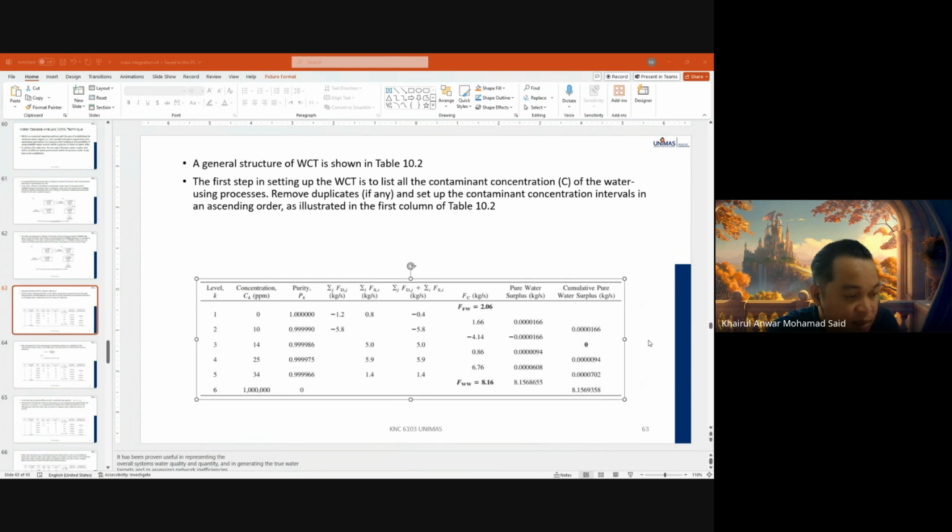The answer is A. Yes. Limiting concentration allows us to define the maximum permissible contamination, opening up the maximum degree of freedom for water reuse. If we only record current operating concentration, we restrict ourselves to historical design. By extracting the true physical limits, we unlock the maximum potential to reuse the spent water.